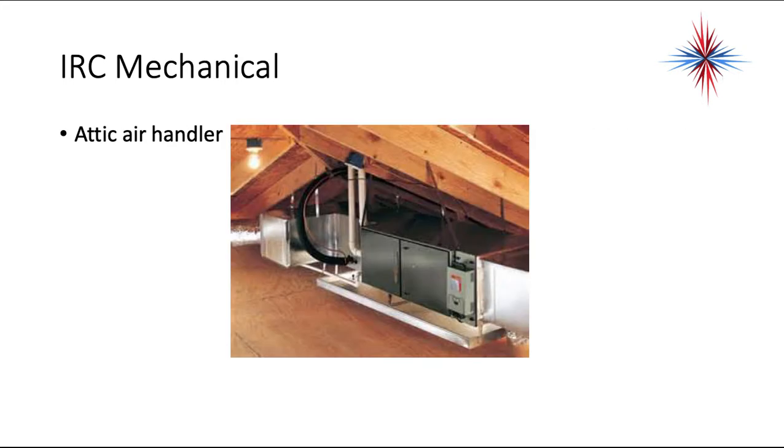Now, there's a few other issues here we need to take into account. Remember the conversation about what the manufacturer recommends. Okay, this is actually an illegal installation. Why? Because of the condensate line. All the manufacturers now are requiring a trap in the condensate lines within 12 inches of the unit. I don't see a trap here.